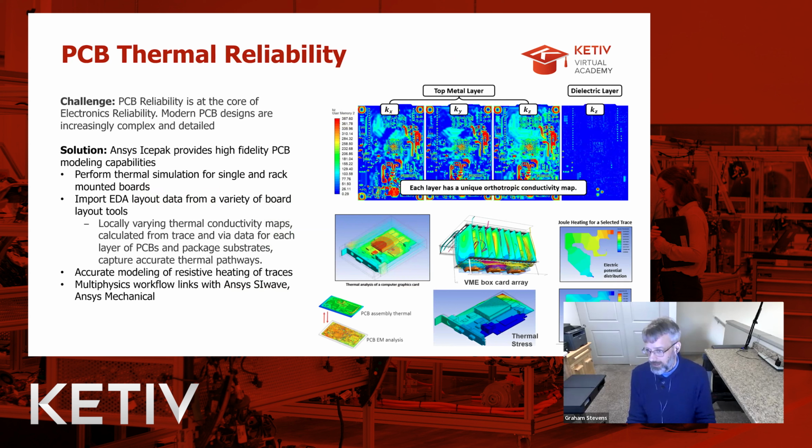So there's a lot more detail here relative to IcePak. I did want to emphasize just a couple of slides relative to electronics. On the PCB side, one issue that is really problematic relative to simulating PCBs thermally or otherwise is that there's a tremendous amount of very fine detail in each of these PCB boards. If you do that in a finite element analysis, you might have way too many elements, which makes it much more intractable.